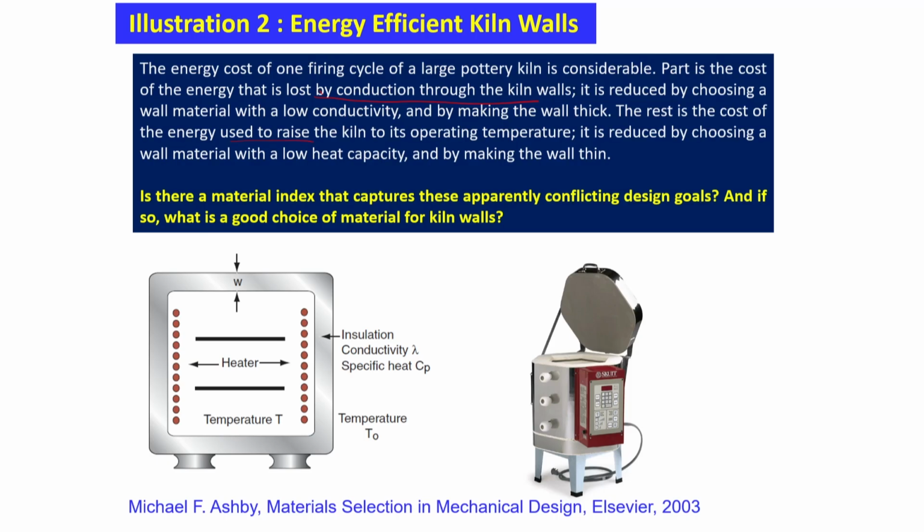So, as you see, bricks normally have a very low thermal diffusivity, the parameter A is very low, and therefore you can calculate the thickness also. You can use concrete also, but concrete is not a good idea. Concrete can withstand high temperature, but it has a much higher value of A. So, you need thicker walls instead of thinner ones.